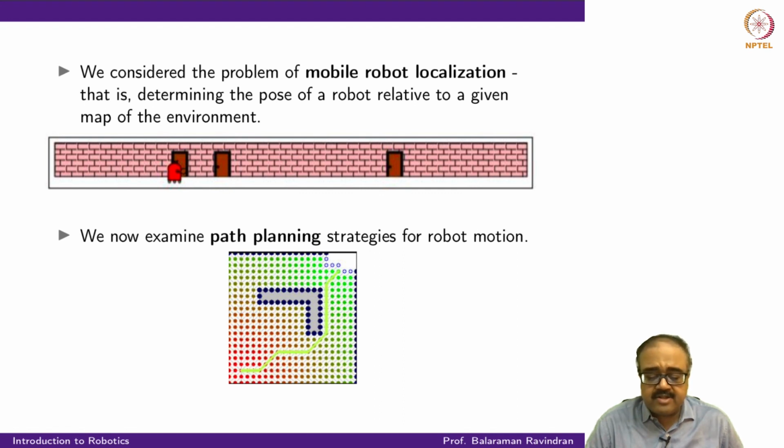So you can think of this free space here as a graph, and breadth first search allows you to search for a path on this graph. Each node has 8 neighbors mostly, and then I have one node which is the start node for me, which is here, and one node that is the end node, which is there, and I'm going to do breadth first search. Basically I'm going to search this graph till I get to the goal.